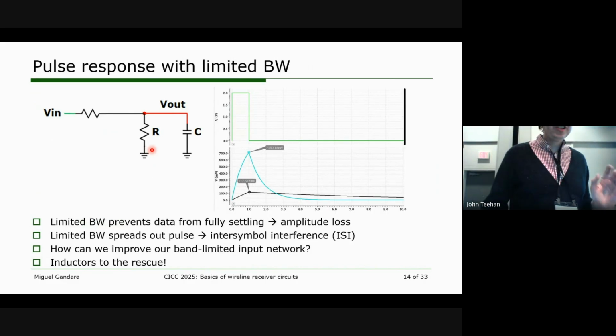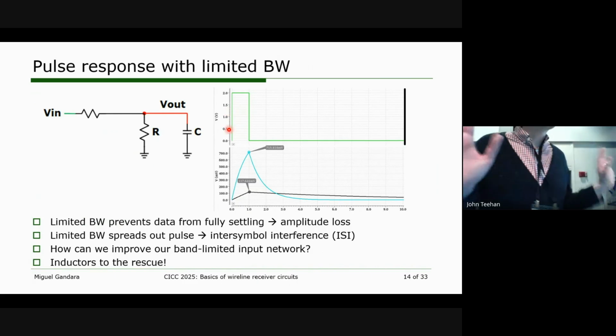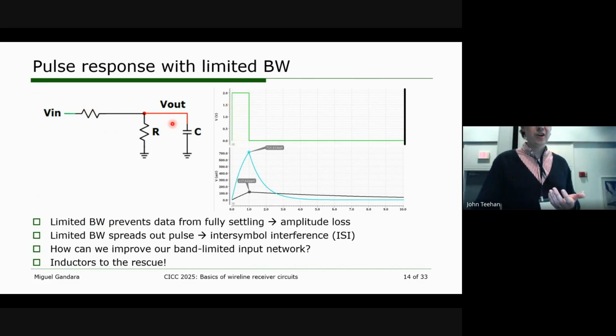Okay, so first, let me tell you what we're putting into the system, right? We're putting in a pulse. The pulse width is a single UI. The height is 2 volts, because if we have ideal termination, this is R, so we get a resistive division of 1/2 from this. So we eventually should get a step of 1 volt at the output.